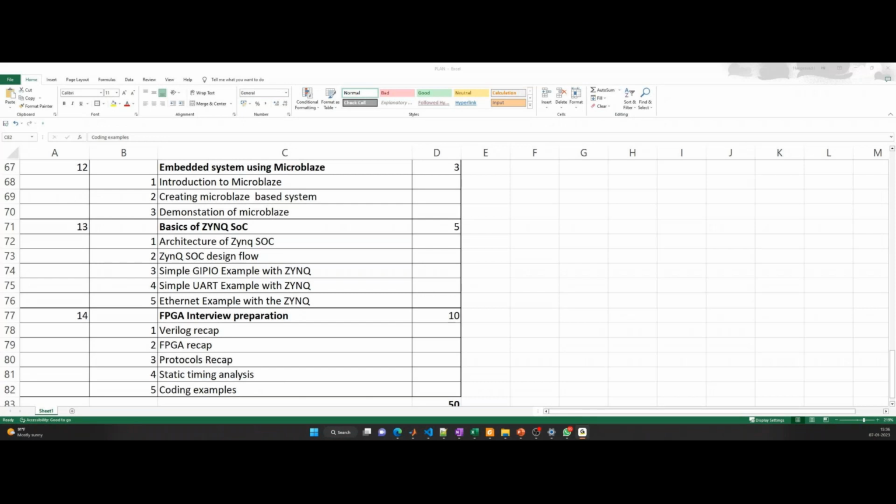Whatever knowledge you have learned in PD is definitely helpful here, like static timing analysis, and there is something called Pblock analysis here, and the DRC things you studied in PD. But the PD domain and FPGA are completely different flows, so in that way it is different.